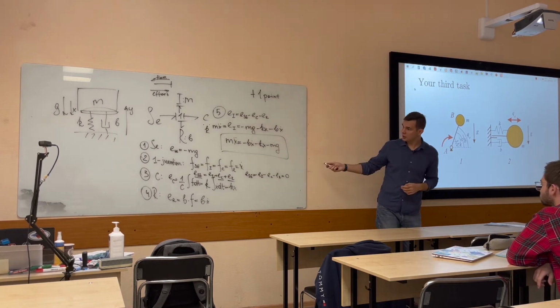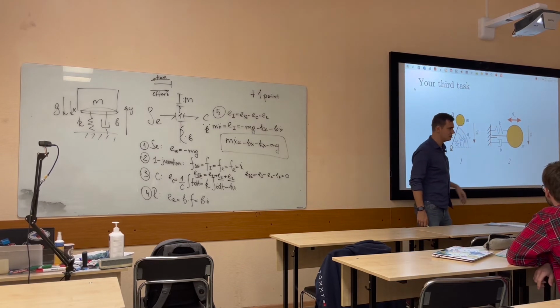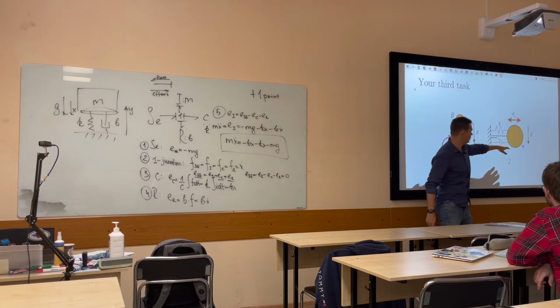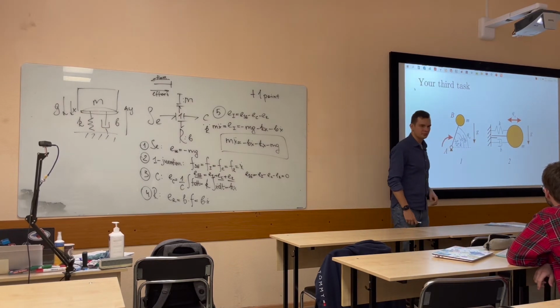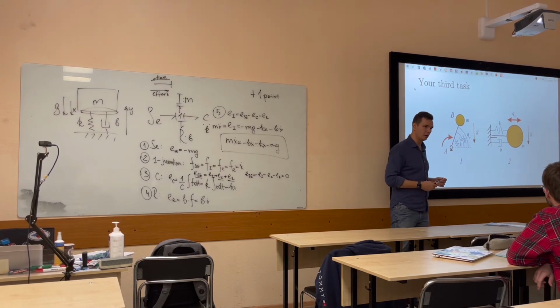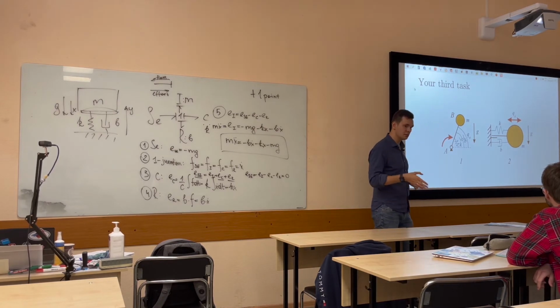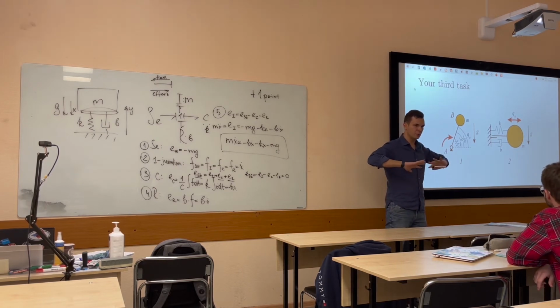The one that I just showed you, it's pretty much the same, but just rotated by 90 degrees. So you need to consider where is your gravitation and the rotation. So you need to derive an equation of motion, then to do a simulation model using those basic Simulink blocks. Then you need to do another simulation model using Simscape blocks, such that your results will be the same.